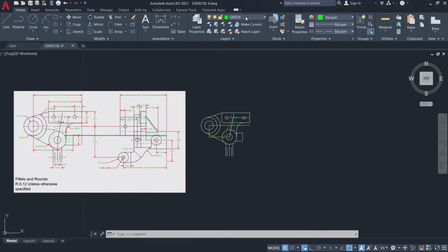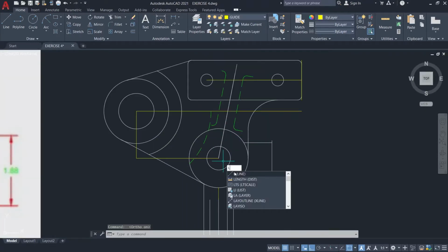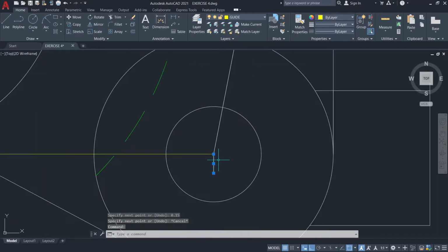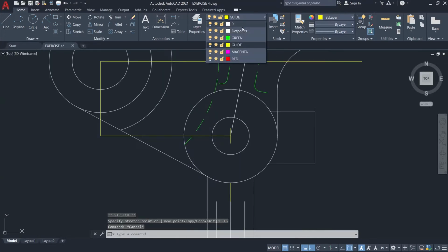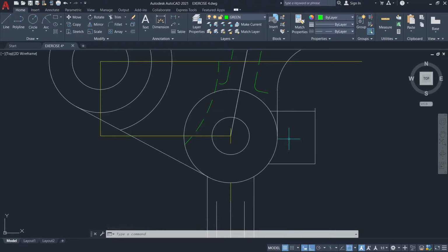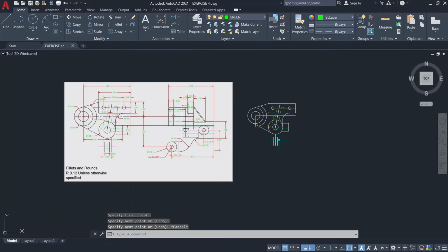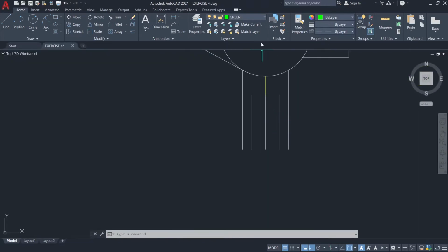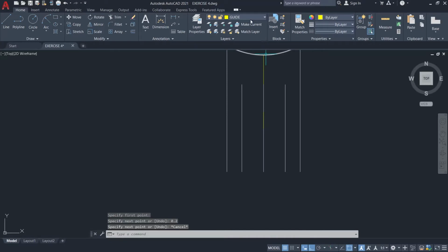again, use a guideline for accuracy, measuring 0.15 downward and upward from the center of the circle. Then, finally create horizontal lines up to this vertical line. While, to make this green dash line, again, make a guideline measuring 0.2 from the midpoint of the center line going upward. Then, make the horizontal green dash line.